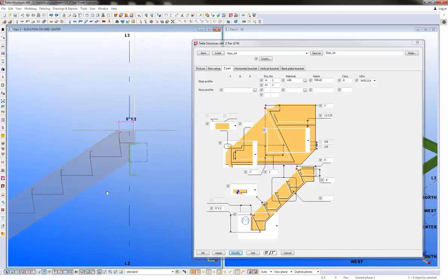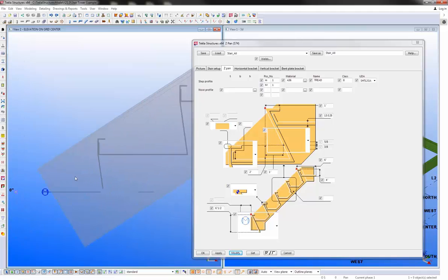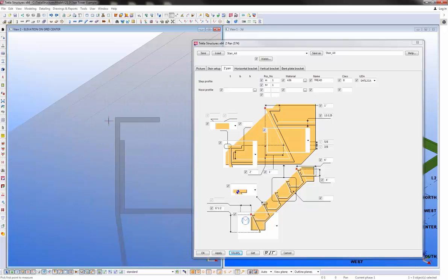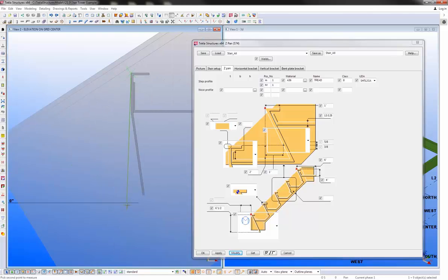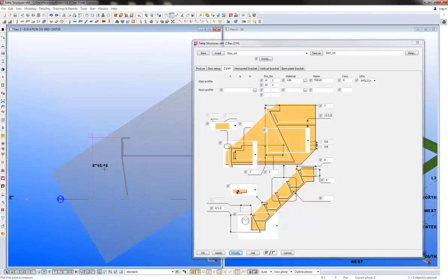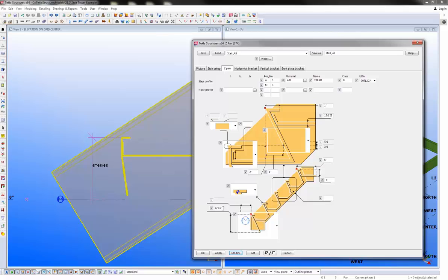And then over here I can come down to the bottom and I can control this bottom pan. Again, I'm not going to worry about the base detail just yet. There's a separate component I can do for that. So let's go ahead and measure this. It should be matching that 6 and 15/16, and it is. So I can come in here and say from the nosing down to the bottom of this pan is 6 and 15/16. It's just a matter of, again, filling in the dimensions for what I want.